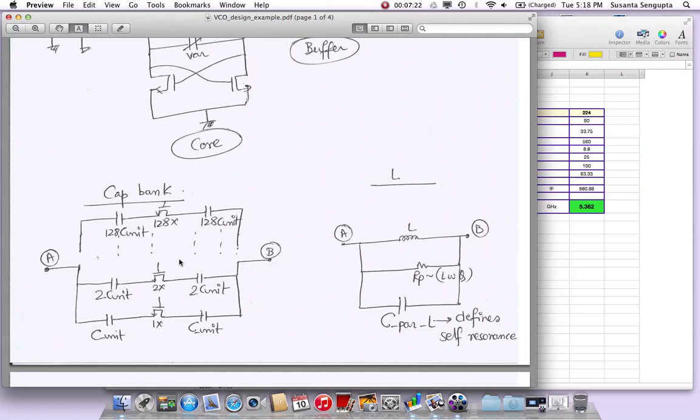This is a similar concept to what my other lecture covers. That's why I've tried to use this same example. So if you've seen that other lecture on CMOS LC VCO design, this is compatible with what we covered there. So this is what the cap bank will look like. So I would like to know what my C unit value should be. What value do I start with? What should my switch size be? I want to know some initial values before jumping to the simulator.